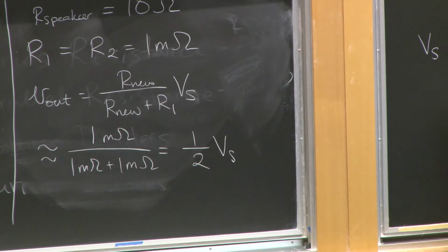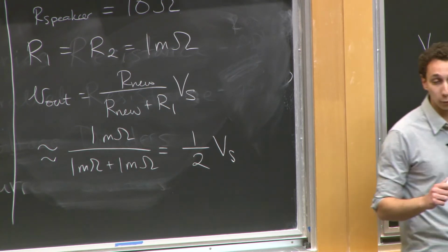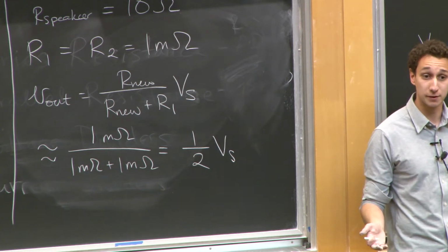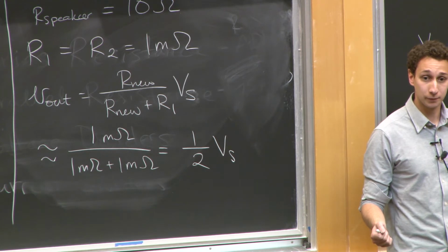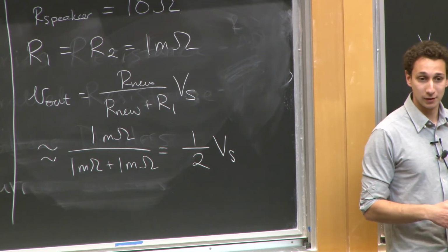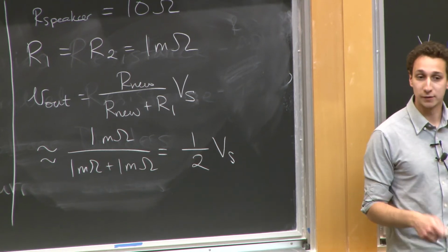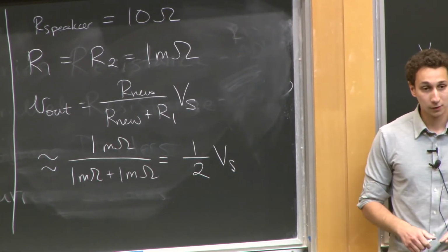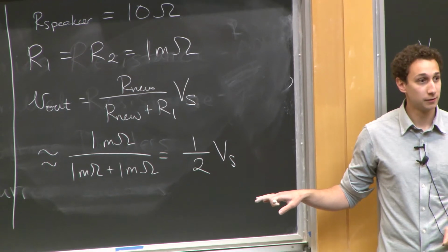When I put two resistors in parallel, the result must be less than the smaller of the two. And in fact, when I have parallel combinations where one resistor is much, much larger than the other, it ends up being very close to the smaller resistance. Maybe you'll get some practice on the homework, and that'll be more clear. Any other questions on this?